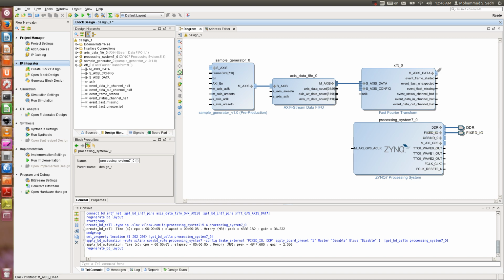So the output of the FFT unit should go to an AXI slave port here somehow, and then to DDR memory. The point is, the AXI slave ports that we have here, as I described in lesson 8, are all memory mapped AXI interfaces, and this is an AXI Stream interface, so there needs to be a conversion between AXI Stream and AXI memory mapped.